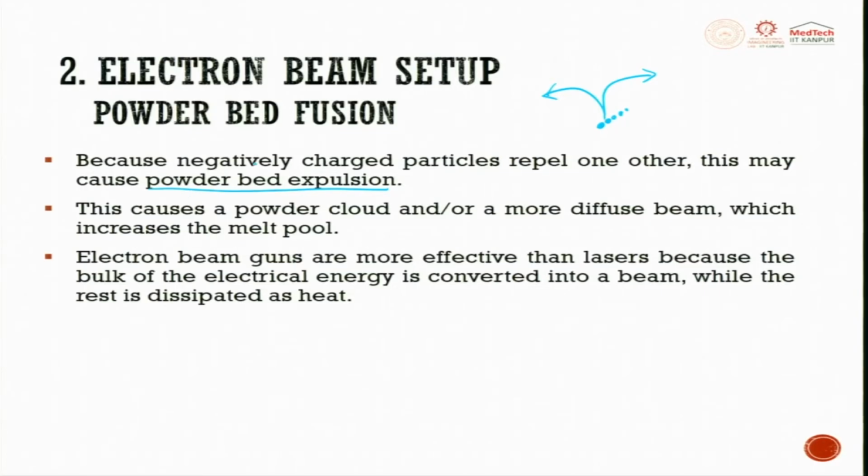Because negatively charged particles repel each other, this may cause powder bed expulsion. This causes a powder cloud and or a more diffused beam. So, when the new beam tries to hit, it gets diffused, which increases the melt pool.